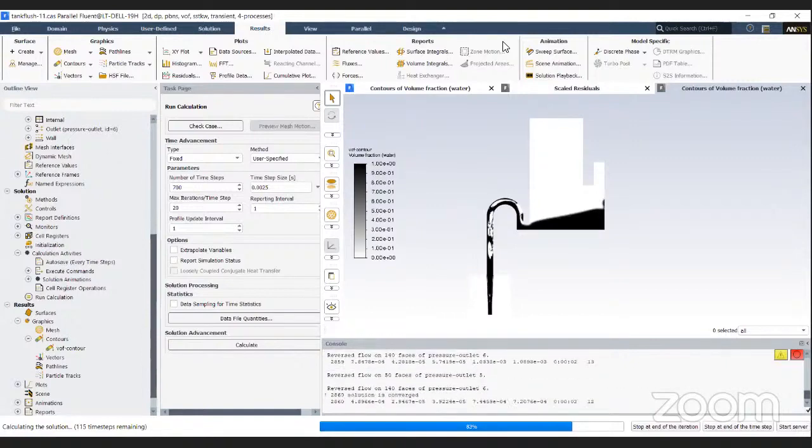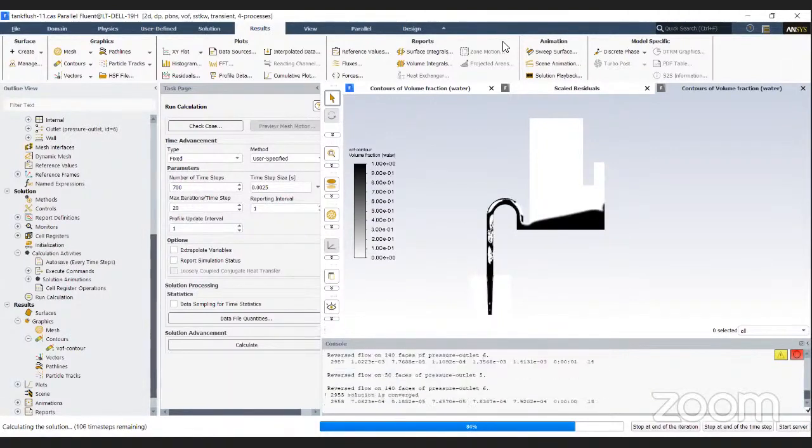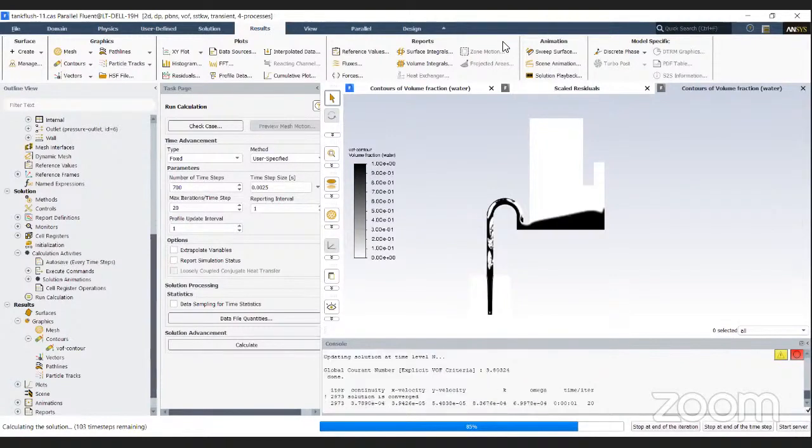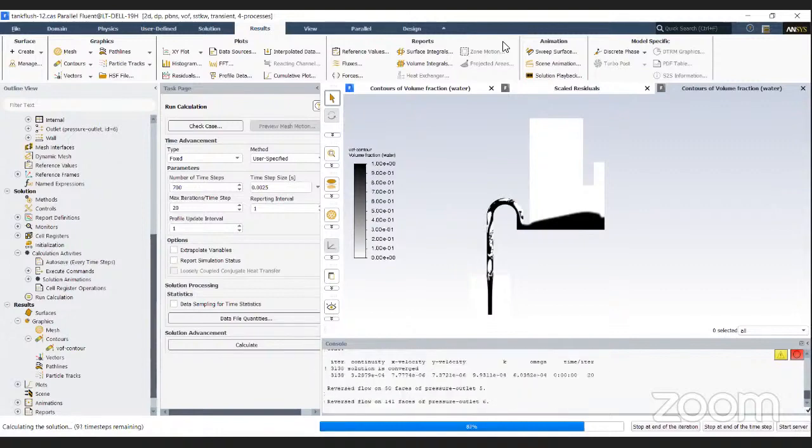It lets you capture the details with more accuracy. So if you want that extra level of accuracy in your simulation, wherein the forces in the domain are playing a big role, for example, in boundary separation or flow separation or something of that sort, then I would suggest go ahead and use the implicit body force option in the VOF setup.